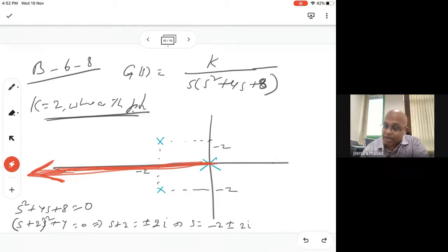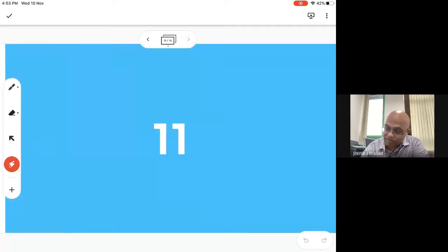Finally, when you have the root locus, as we discussed and also covered in the video lectures, then the question here is, if k equals 2, then what is the position of the roots of the closed loop system? In that case, we have to locate those values. For different k, we have to find out the roots, right? So we can also write the equation.